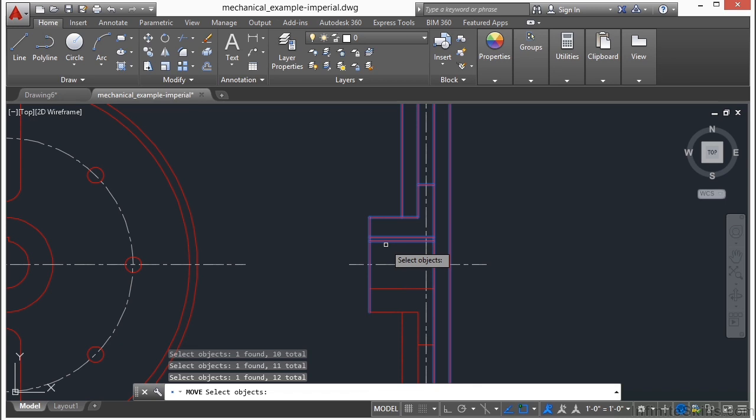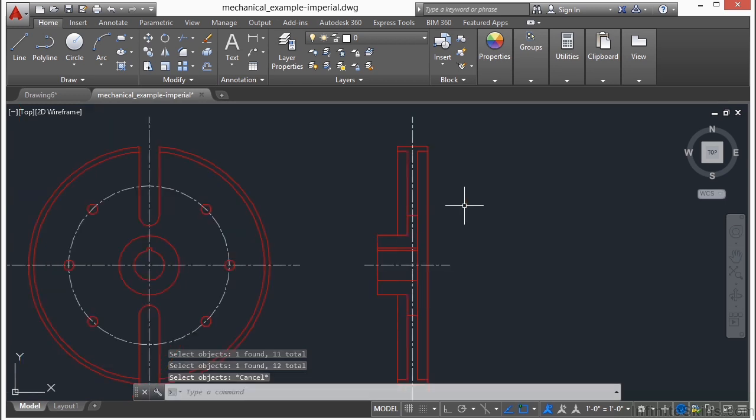So the other 2 methods that we can use are a window selection or a crossing selection. And now there's a new selection mode in here also called a polygon select option. So let's look at the crossing windows first. I'm going to escape out of this command so we can start it brand new.